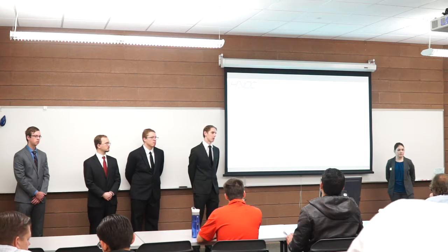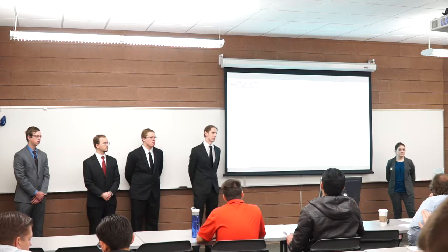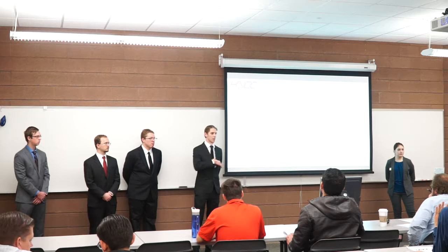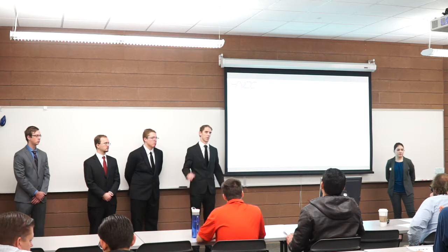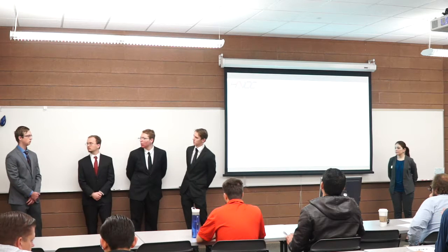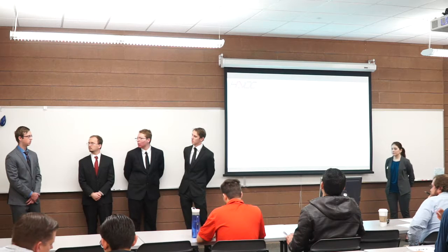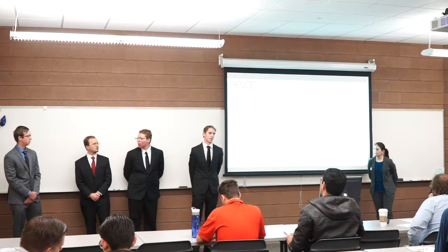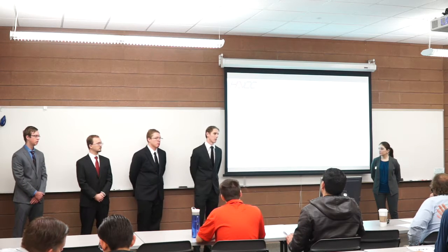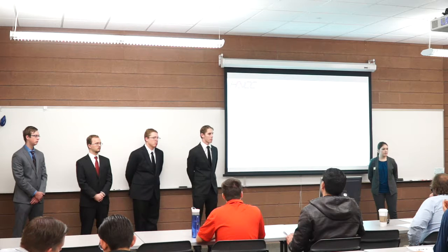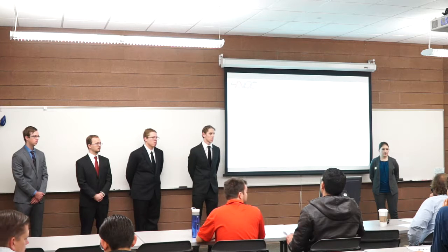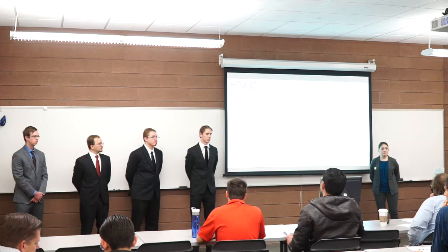So according to our calculations, based on our rough estimate for how much torque we need, if we rotate 180 degrees, we'll be able to actuate, if we have servo horns of the correct size, which I think was, what did you say was 3 point? It was a 2 centimeter diameter. Yeah, sorry, 2 centimeter diameter, that's right. Then with 180 degrees, we can fully actuate the finger. Okay, so you can't permanently attach the tendon to the horn. Yeah. So hang on, friction for that. Yeah.